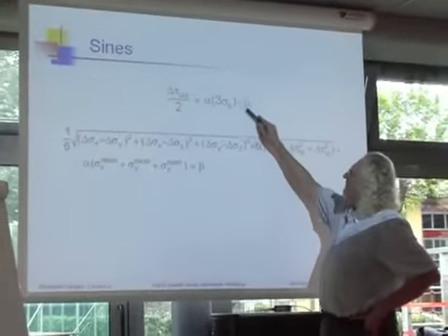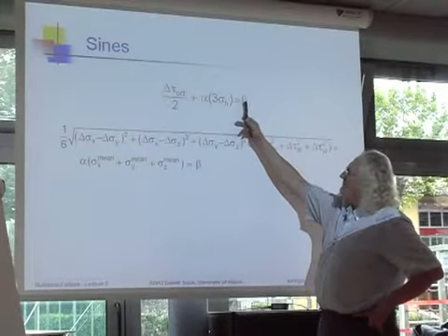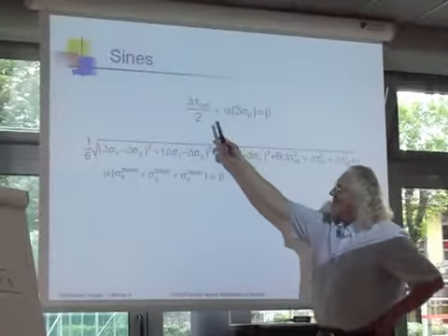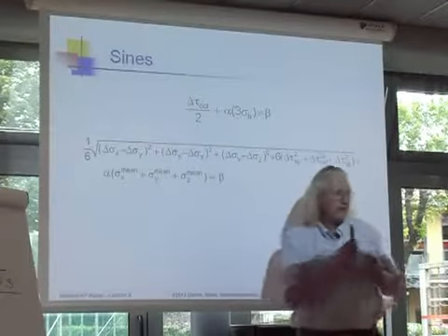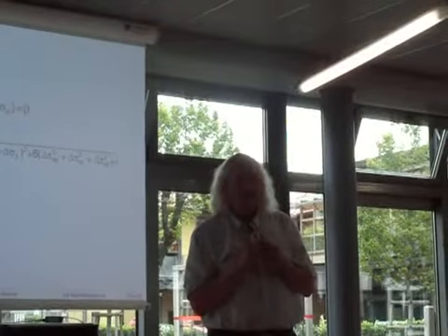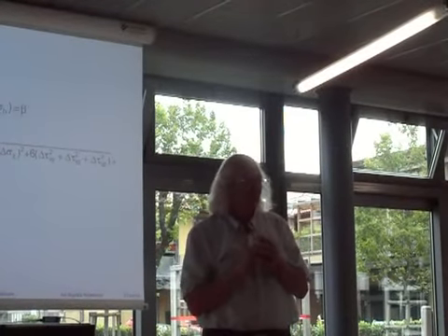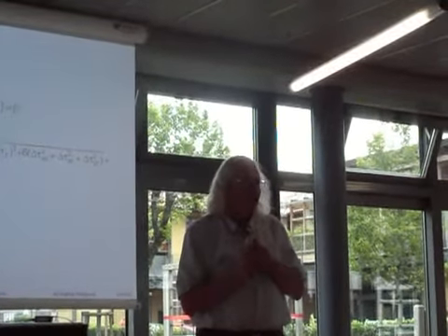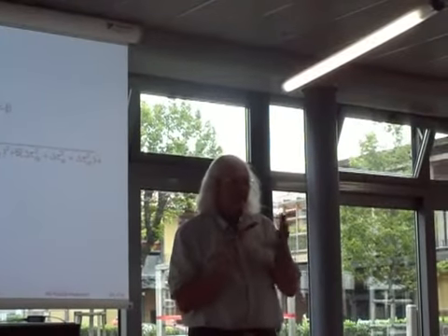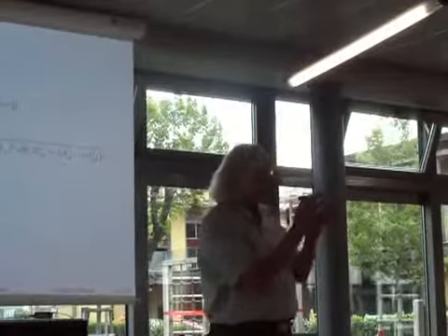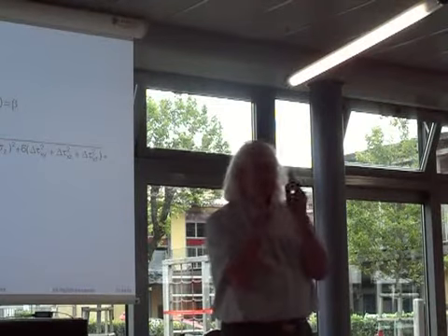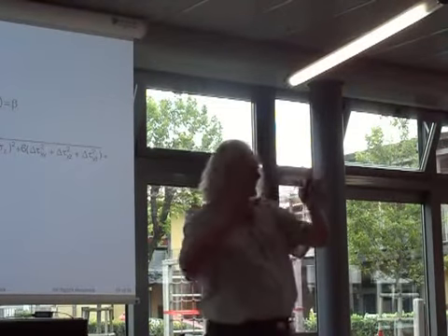And I set that equal to some property of the material. And this property of the material will be the fatigue limit normalized to the octahedral shear stress. Okay? And this was exactly Sines' logic. So, you know, people have the idea that there's some theory behind fatigue models. I would say there's absolutely no theory behind any fatigue model. I know that's not very comforting, but these fatigue models come from people making observations. They make observations of the science, and they propose some mathematics that puts the variables in the correct place.